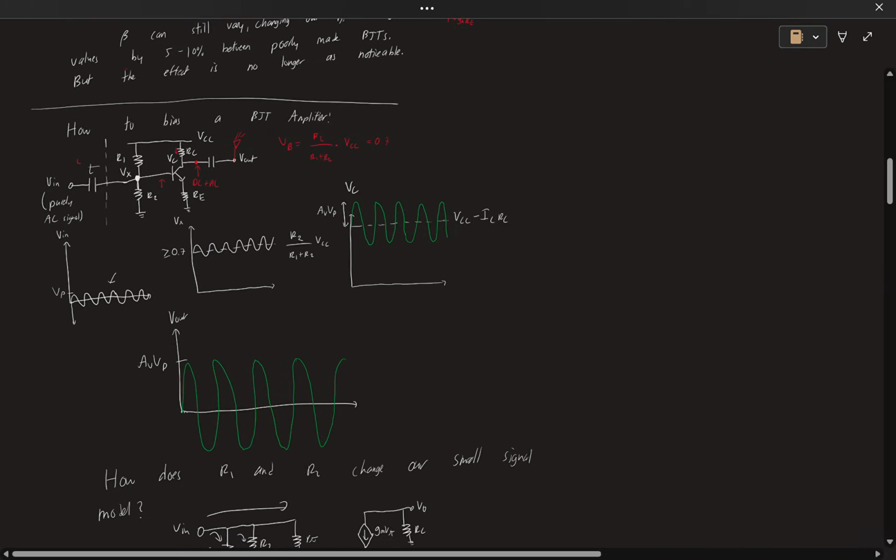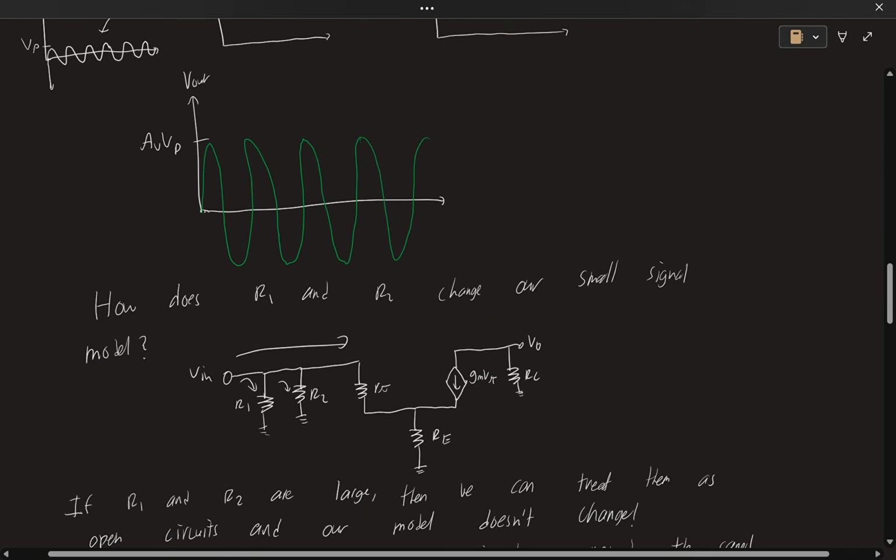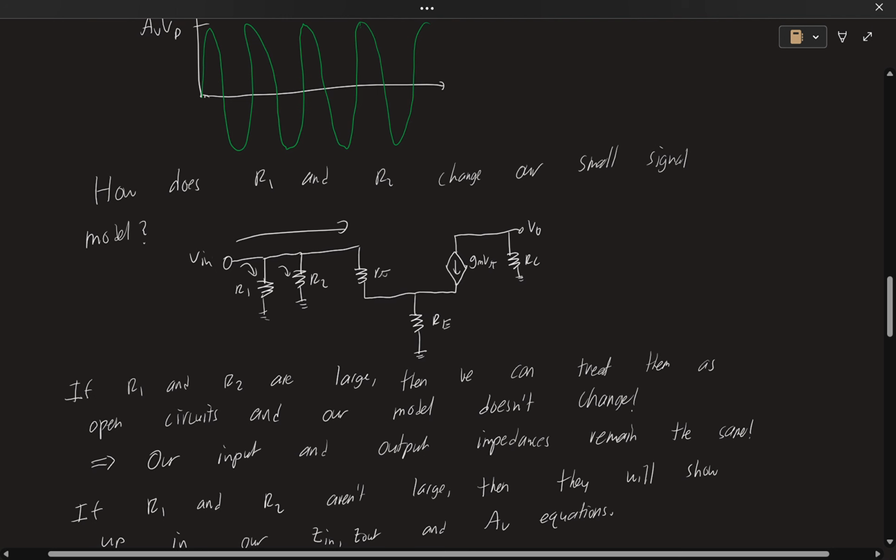And the solution to this is you have to now lower your R1 and R2 so that they show up in your output impedance equations, and there's no need to derive it. It's just one of those, like, while you're in LTSpice, the goal is, okay, you get the right gain, but now you're not able to get the right output impedance.